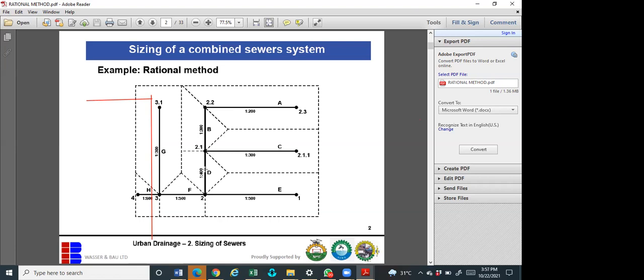That's why most people that design their houses and use 1 inch pipe to take water from the overhead tank have water problems if there are more than 20 people in that house or more than 10 taps. So the ideal thing is to use about 2 inches pipe. And where there are many people, use 3 inches pipe for the main coming from the overhead tank. When it gets to the different houses, you can take it down to 2 inches. Then when it enters your houses, it can go back to 1 inch.